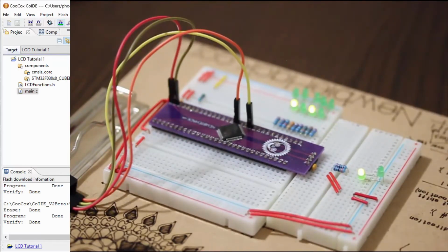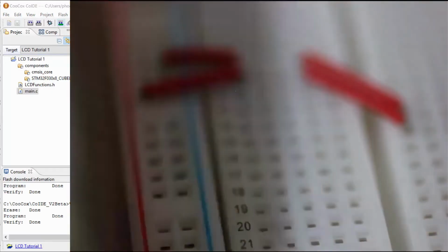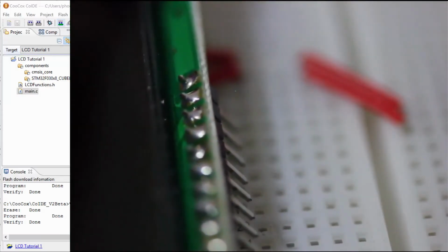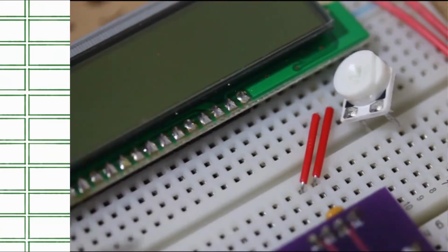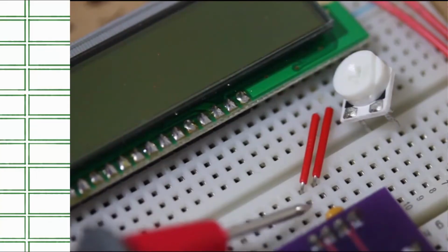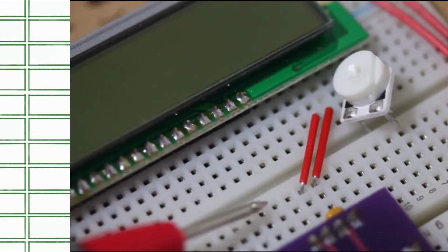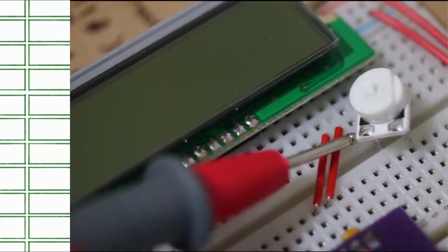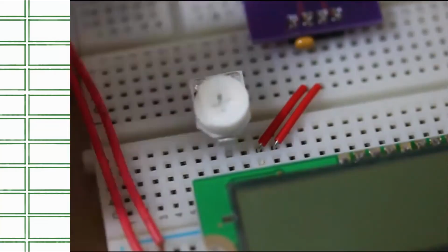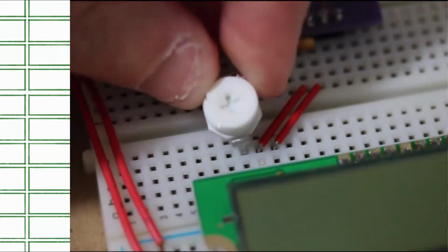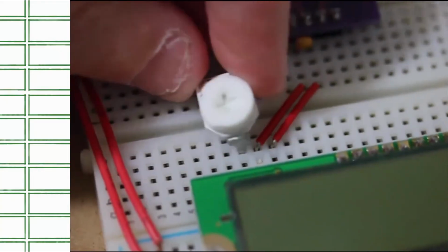Looks like it's working. We should be able to go ahead and add the LCD. I'm going to remove these two LEDs. I'm going to go ahead and put the LCD from pin 30. So we're going to need to find out where we're going to put a potentiometer. All these tie strips are going to be reserved. And also we have these two pins here that are going to be brought over as the register select and the read write. So I think the only place to put the potentiometer is over here. So let's go ahead and do that somewhere over here, probably as close to these wires as possible so I can utilize as much of this board for other purposes later on.